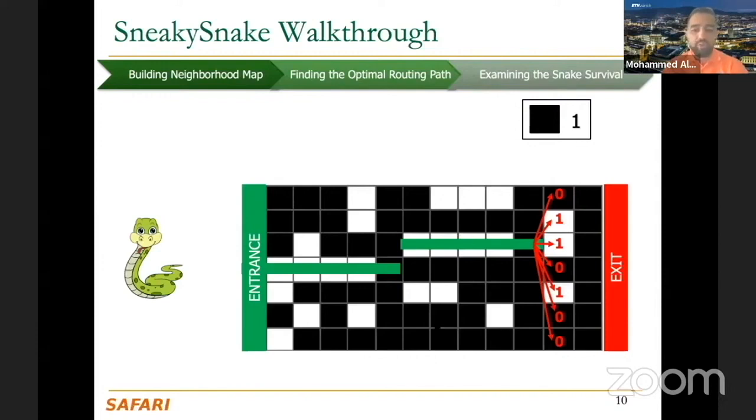Now, some of you could say, how come it doesn't matter? Because if I choose one far from this path, I'm going to use a vertical path as well, and that is a cost for the silicon or for the metal layer in the VLSI chip, right? Because we have multiple layers stacked on top of each other to have vertical and horizontal connections, and connecting these layers far from each other might give you some cost, because you are going to occupy this entire vertical connection.